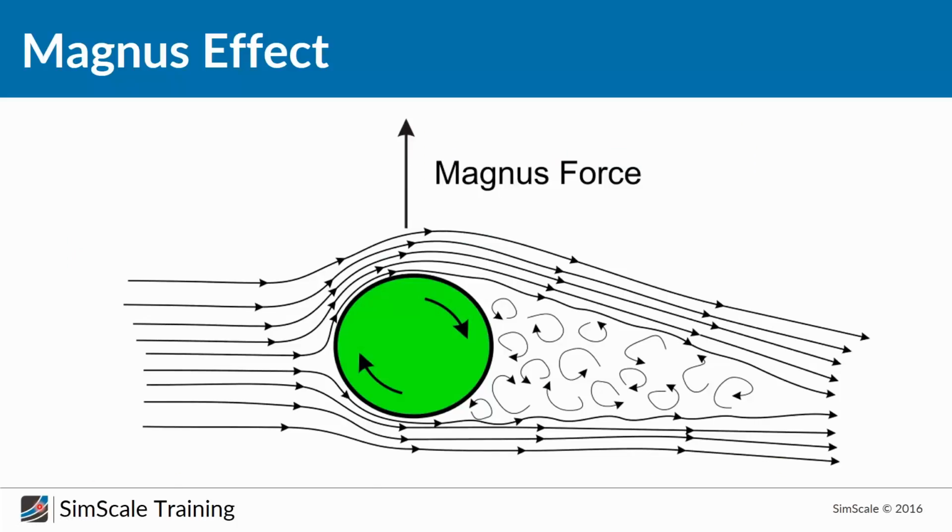The reason for this strange flight behavior of the ball is the so-called Magnus Effect. Basically, the Magnus Effect is the effect in which a spinning ball curves away from its principal flight path. Just imagine we have a ball, we add a spin, it's rotating, and then we have two possibilities. We can have topspin, which means the surface of the ball is moving forward with the spin. So if we're flying in this direction, this would be topspin, and backspin is the other way around.